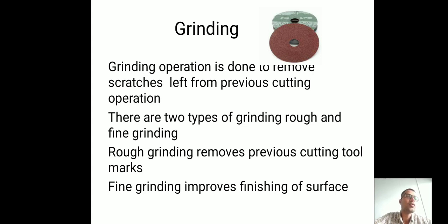While cutting with the help of a machine, certain corner edges and certain scratches are left on the surfaces of that specimen. With the help of grinding paper and the grinding operation, we can remove or minimize the scratches, so that the whole surface of that specimen will become smooth.